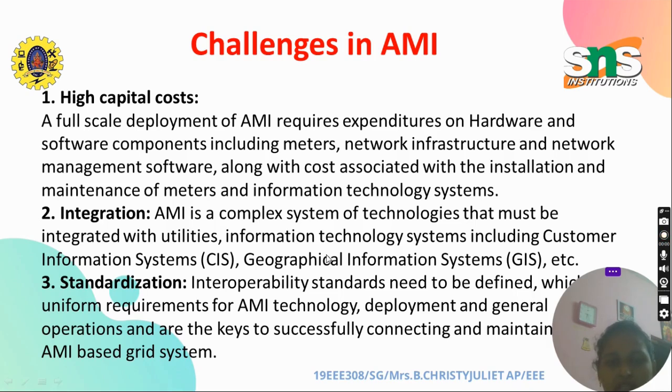In order to have communication between the utility sector and the consumer sector, we need smart meters installed at every consumer premises, which makes the grid smarter, so that the grid can automatically detect consumer usage, make decisions, track data about outages, and also track the peak energy consumption of every consumer and do billing, thereby providing the electric power features that an electric grid needs to have. So this AMI is the main thing that makes the grid even smarter.